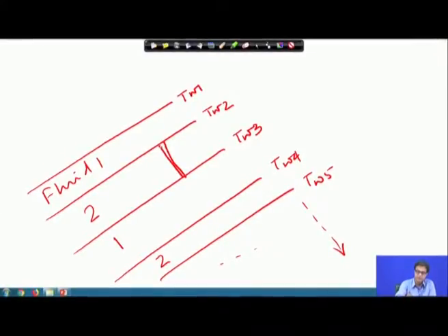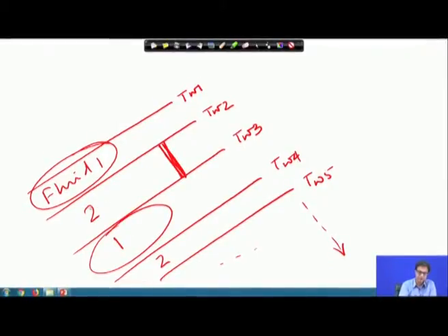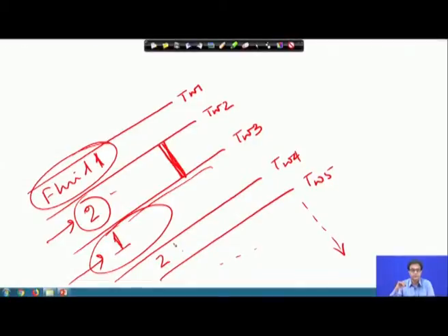But for a particular layer, on one side we have fluid 1 and on the other side fluid 2. If we consider fluid 2, on both sides it has fluid 1. Similarly, if we consider fluid 1, on either side it has fluid 2. This is particularly the case in a symmetric configuration of a two stream heat exchanger, where most of the time you will find a combination like 1 2 1 2 1 2 and so on.